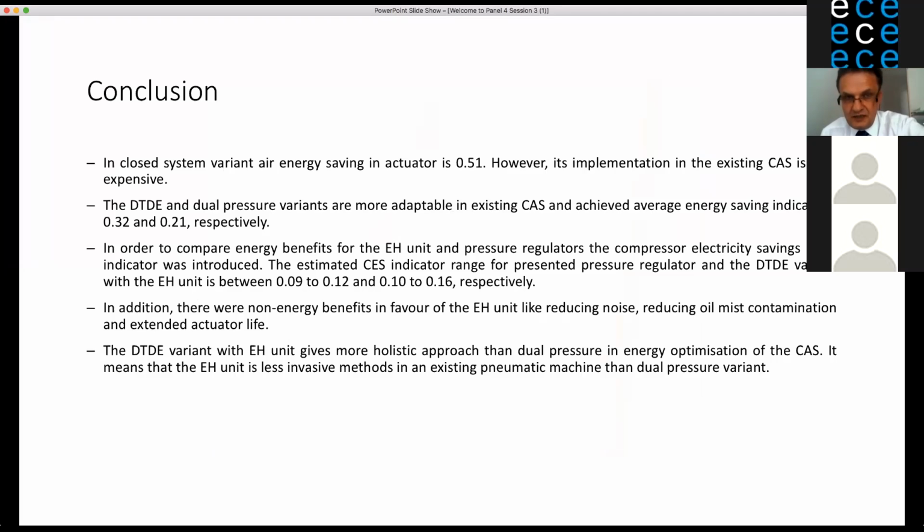So we made 6 industrial tests, in which the feeding pressure, the gauge pressure, was 6 bar. So we find that we can put the back pressure 1.5 bar, which is okay for normal or regular work of this pneumatic installation.